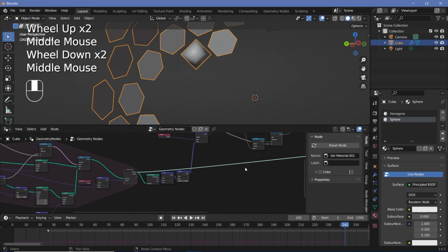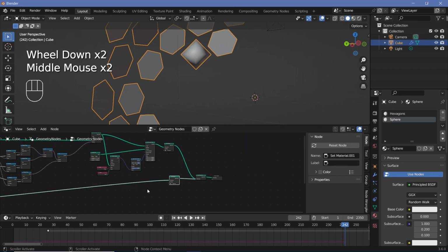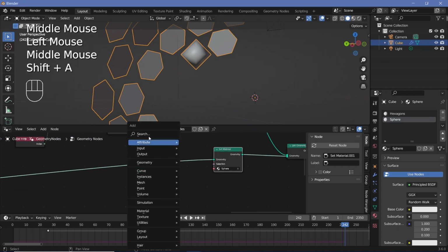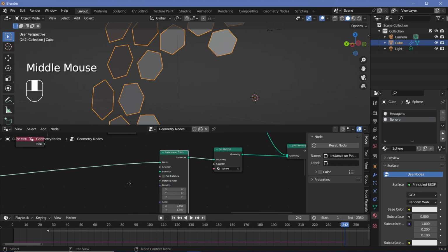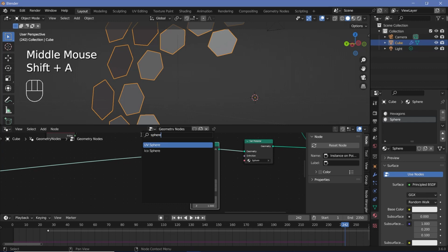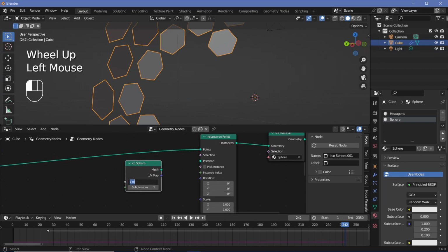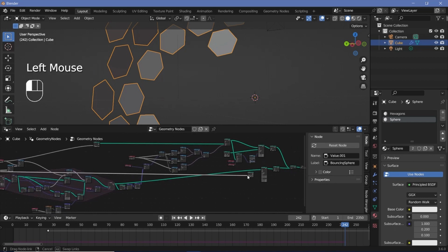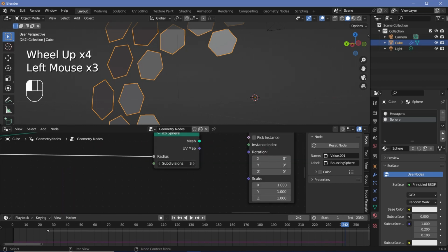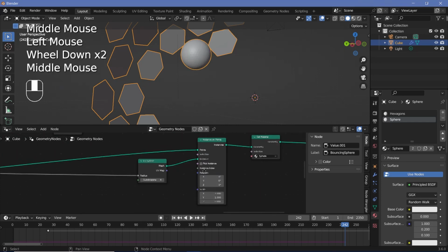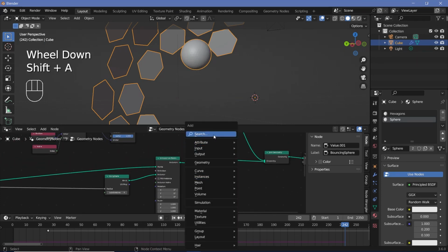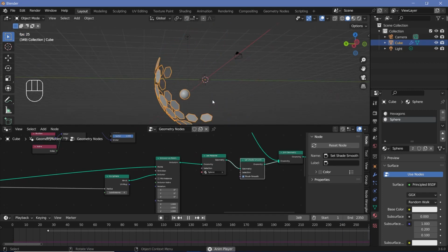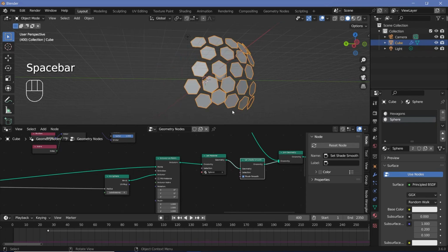Remember, this node is coming all the way from the output, which is the point, but we actually still have it as a point and not a sphere. So first we'll just assign the material as sphere, and then we'll press Shift A and search for an instance on points node, and we'll instance onto it a sphere. So just search for an icosphere, change the radius down to the radius that we selected right at the beginning. Let's select this, plug this into the radius, and subdivisions, let's give it a subdivision, so something like 3 or 4, plug that into the instance, and then we have to set shade smooth. So search for a set shade smooth node, plug that in, and you are officially done with the geometry node section. Now we'll just do the materials, backgrounds, set everything up, and be done with it.